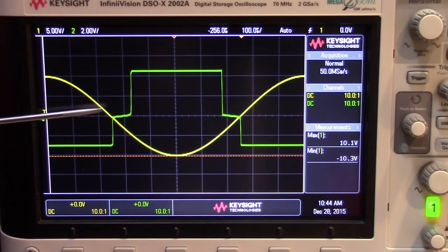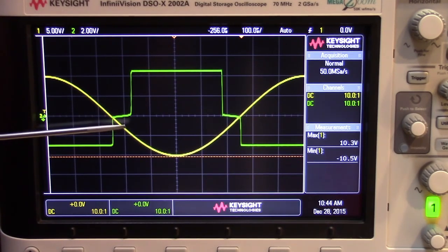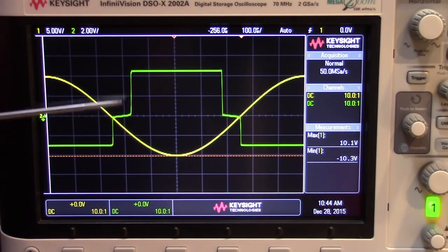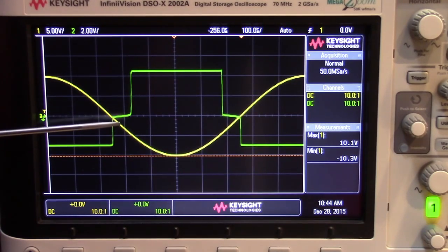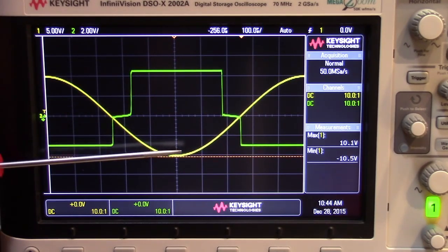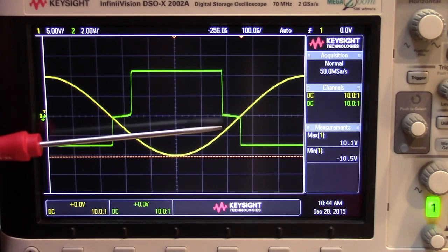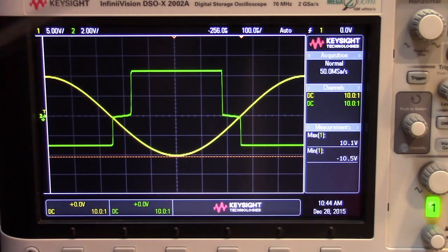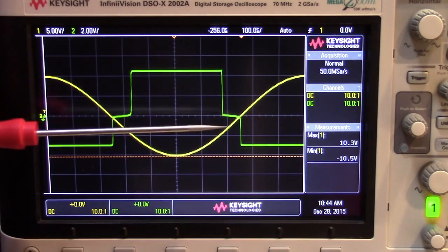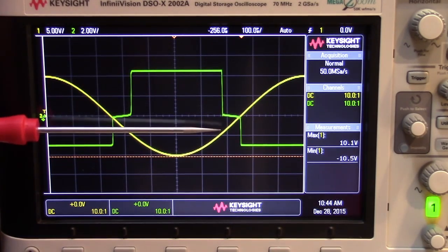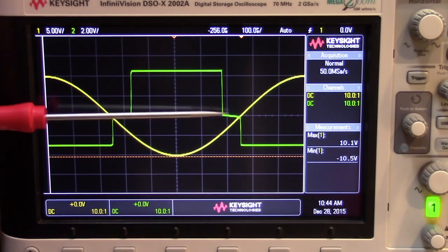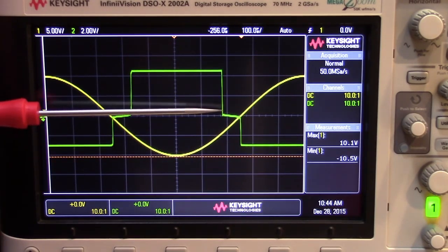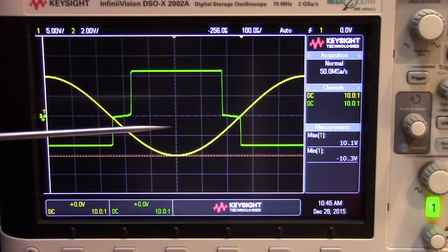And we can see that as we go negative, once we hit that 4.4 volt mark, the output of the op amp goes high, just as it did before, and it'll stay high until we come back up above that 4.4 volt mark. And again, just as before, in between our negative trip point and 0 volts, the output of the op amp is 0, or quite close to it.